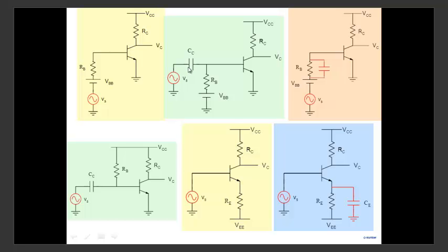So this solution is okay if you want to go into the lab and make it on a breadboard or a PCB. But if you want to implement this on a piece of silicon, you can't do that. You could implement maybe all this part here, but the capacitor will have to be an external capacitor. You can't build the capacitor inside the silicon. Microfarad capacitors can't be built.